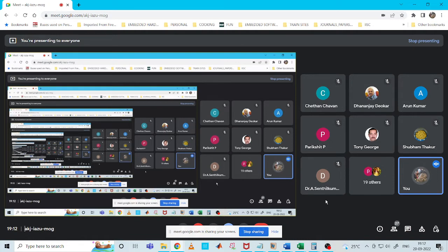I used to work on helicopters and fighter planes. There we have something called AHRS, the attitude heading reference system. If the AHRS fails, the first thing the pilot will do is either eject or land the plane. He will not compromise. So it is that important. The concept is the same, just that in aircraft it is not MEMS based. They are more light based.